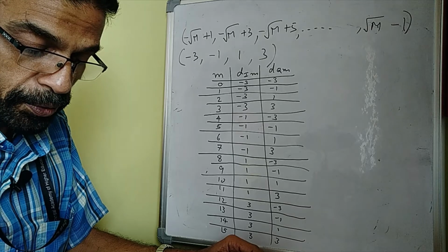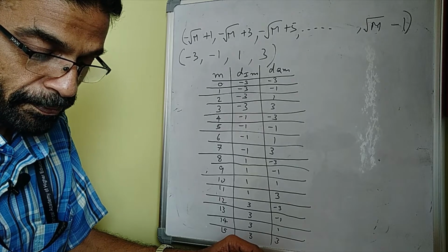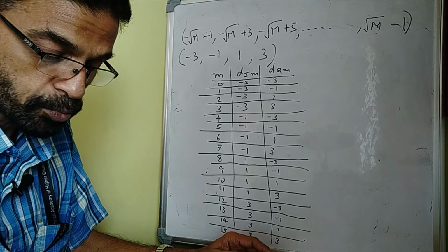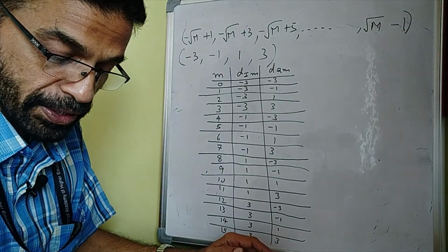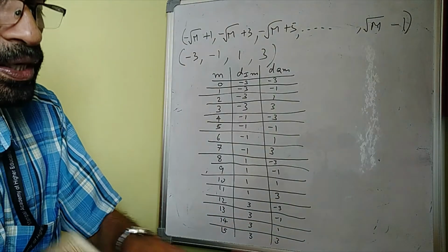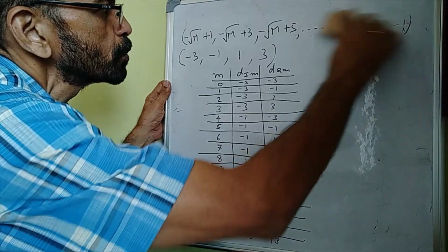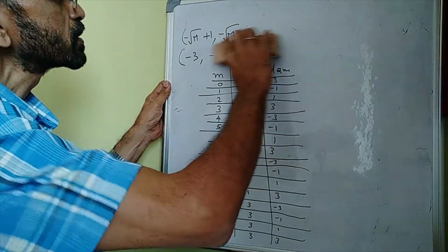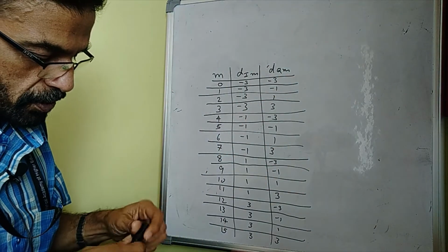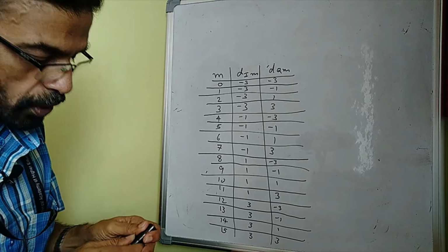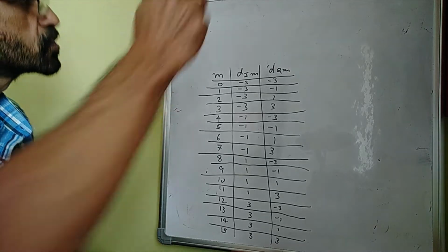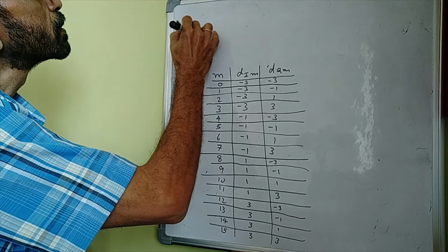And before I go to the signal space, let me just say that the fact that the QAM signal has both its amplitude as well as its phase modulated can be obvious from the way the signal looks. If you do a small manipulation to that signal SMT which I wrote earlier, it becomes more apparent how the amplitude as well as phase is getting modulated by the symbol.